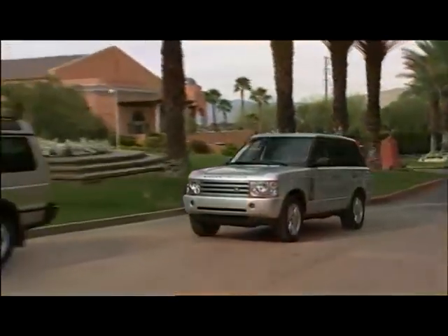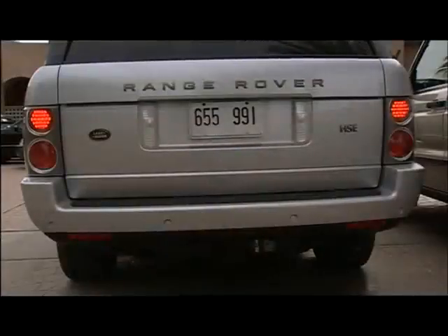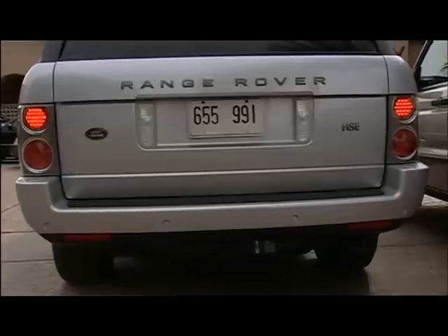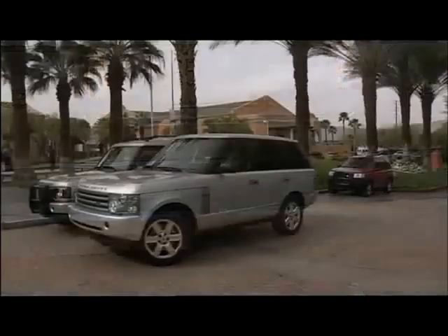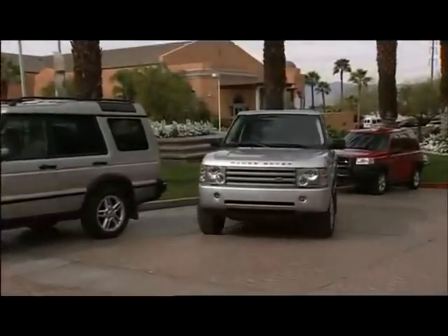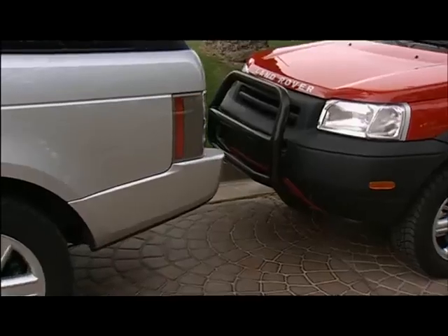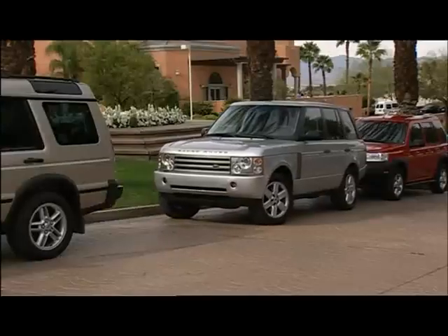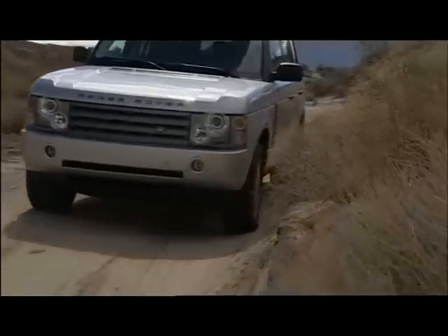Park distance control assists when parking or locating obstacles nearby. 4 sensors on the front bumper and 2 on the corners of the rear bumper have a range of about 2 feet. 2 additional sensors in the center rear have an extended range of about 5 feet. The distance from an object is signaled by an intermittent tone, a high pitch for the front, a low one for the rear. As you move closer, the frequency increases. When the distance is less than 1 foot, the tone becomes steady. The park distance control can be muted when the signals may not be appropriate. Your owner's handbook has full details.